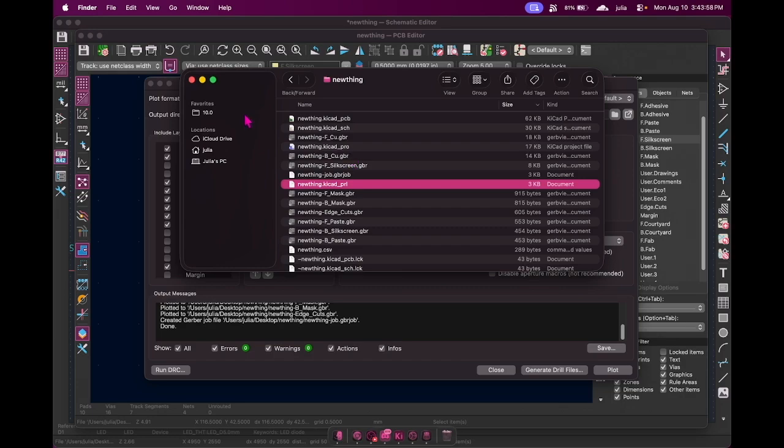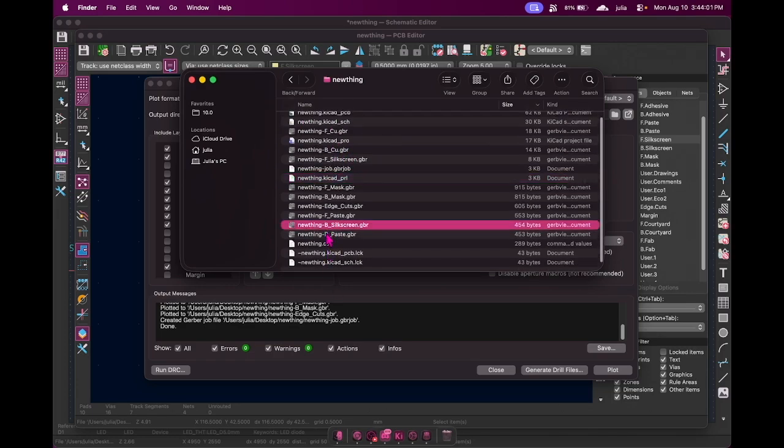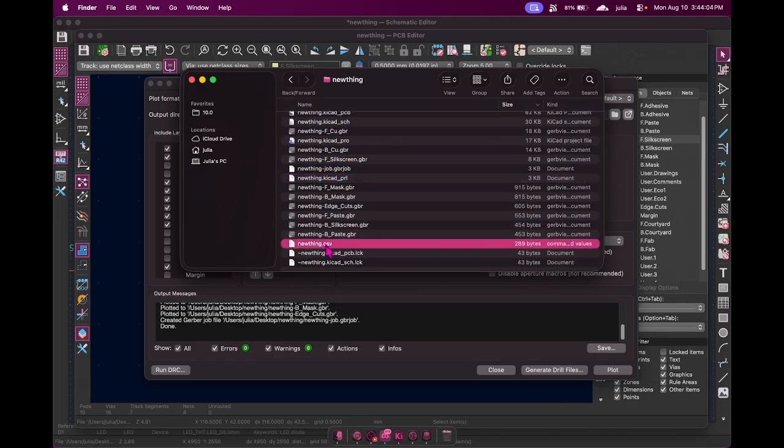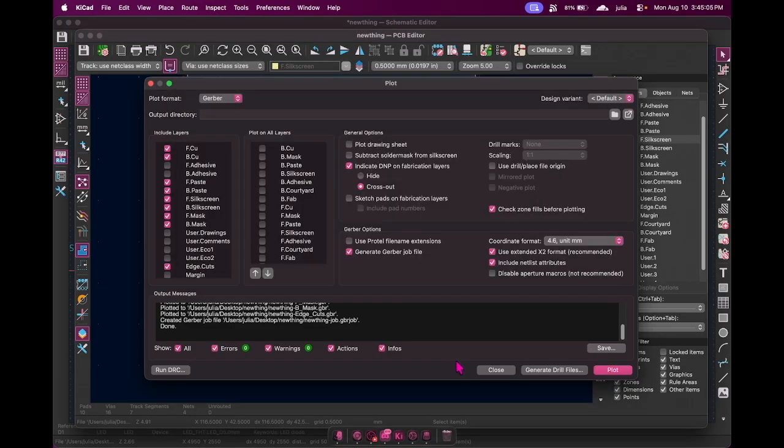And then for getting the components themselves, you'd go to a manufacturer like Mouser Electronics and give them your CSV, and they have a feature for automatically reading it and getting the components. It's a bit difficult to use, so you're going to have to look for some of them manually. Anyways, that's how you make your Gerber files and your CSV for your bill of materials. And guess what, guys? That's it. That's everything. You're done.